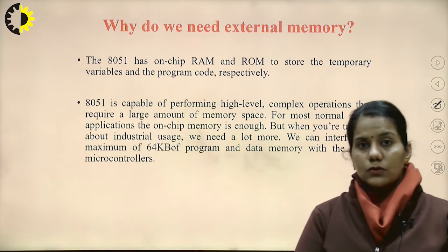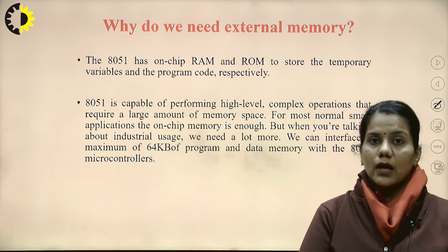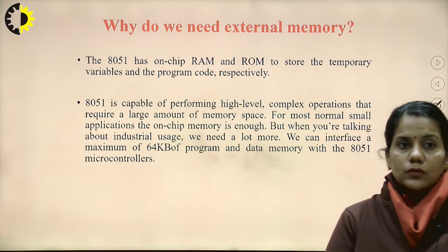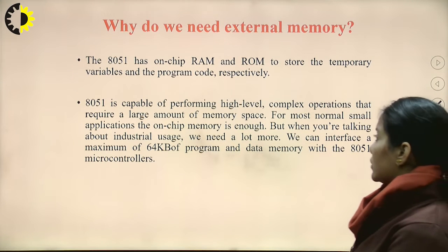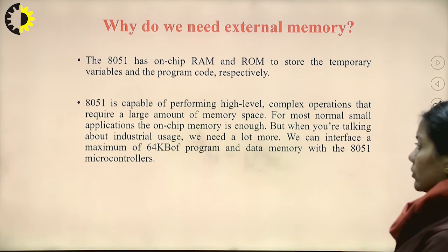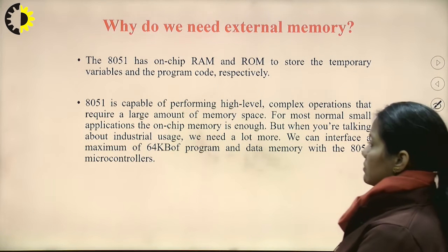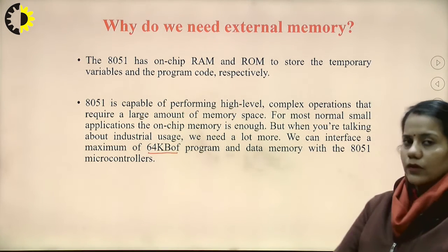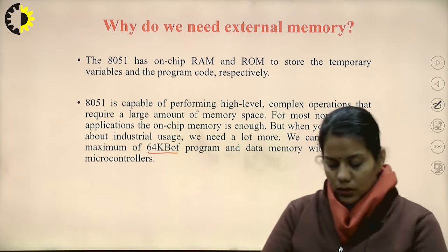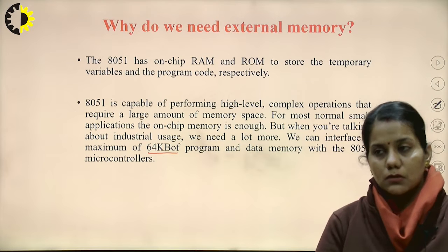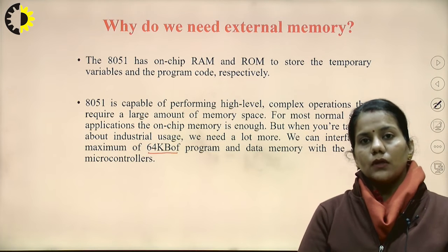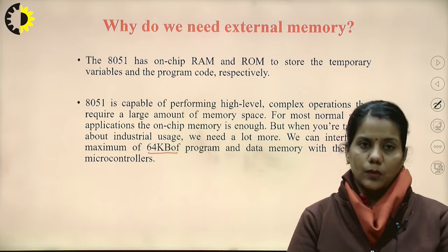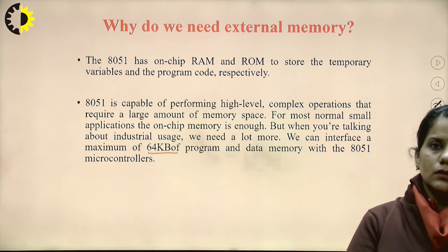But if we are using 8051 to implement higher level applications, or we can say when we are talking about industrial usage, we need a lot more memory. We can interface a maximum of 64 kilobytes of program and data memory with 8051 microcontrollers. So in this lecture and the subsequent lecture, we will see how to interface this external memory, that is the program memory as well as the data memory, with our 8051.